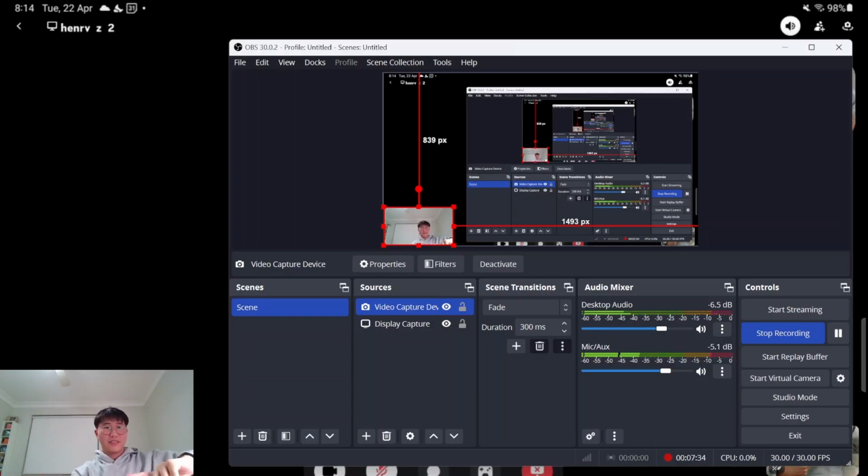Okay, fantastic. So pretend this is a frame, right? My fingers, where this bottom finger is the ground, and the other ones represent the two columns and the beam at the top, right? So if there is a horizontal force, like a wind or something, that knocks this frame to the side, it's going to sway like that, right? Because it's not braced, essentially. It's prone to this kind of behavior, essentially, right?